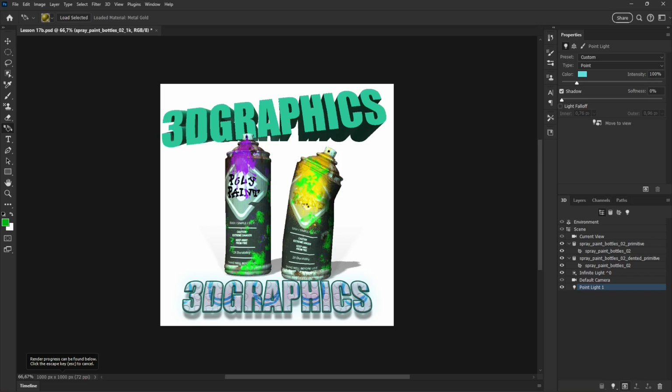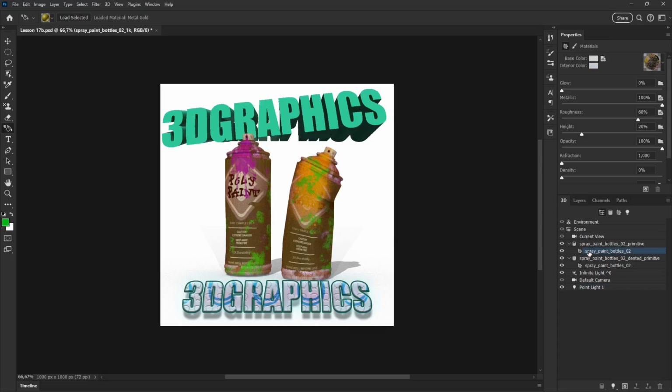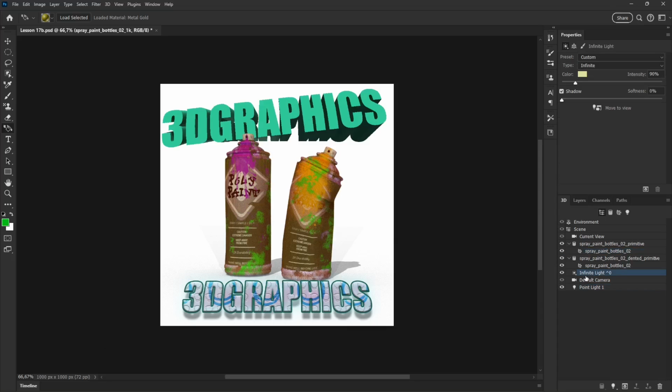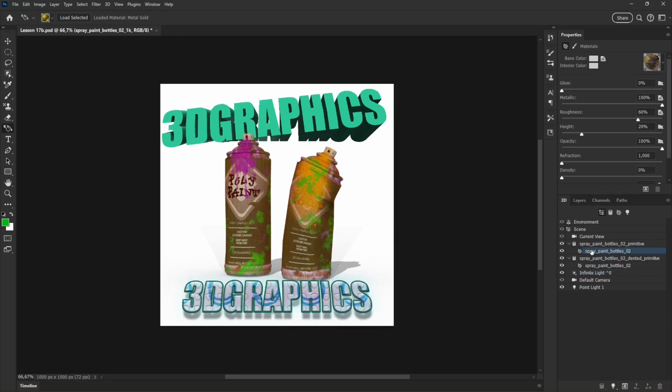So when you run a render, it's going to calculate the 3D object, the texture, and the lights, and it's going to be faster if you have a faster graphics card. Now, if you see too much light, you can adjust the light intensity, but sometimes it's caused by the material. So maybe it's too reflective or something like that. And essentially you can fix it.